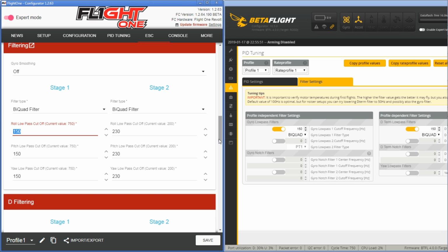Okay, so with that, hopefully with this video you have some idea of where you want to focus your attention. I gave you some of the settings I would give a try. FlightOne, you do have those awesome presets, which I really wish Betaflight would have. So for some different filter setups, give those a whirl. It's kind of a feel thing, feel your motors kind of thing, and maybe give my filter settings a try as well. Betaflight, same thing, because these are not the defaults. These will be the defaults for Betaflight 4.0. So it's an evolution there as well.